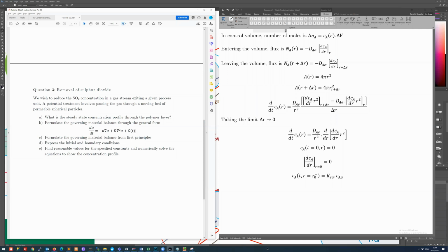So in the energy balance, where for alpha you were using T for temperature, you had the conductivity and d2T/dx squared. So that was your conduction term. So you had conduction and convection. In momentum, you had viscosity and convection. In material balances, you have diffusion and convection.